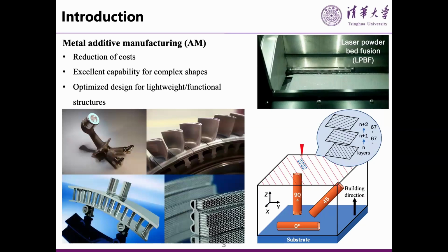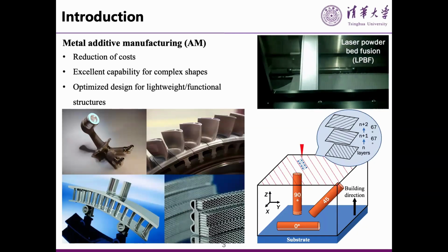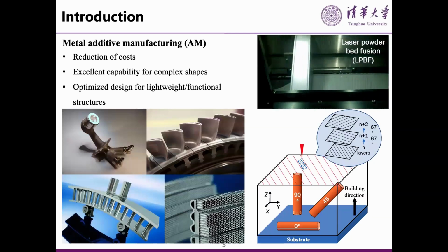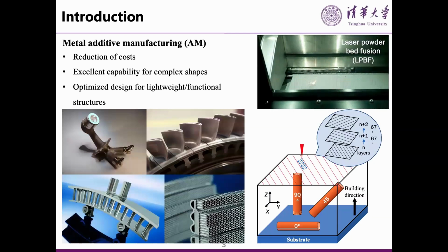Inconel 718 is the most popular material, the most important superalloy in the turbine industry. Inconel 624, 625, the other, is mainly a cast material. And Inconel 718 is actually usually a forged material. It's used for rotating parts actually. Okay, therefore material property becomes very important.